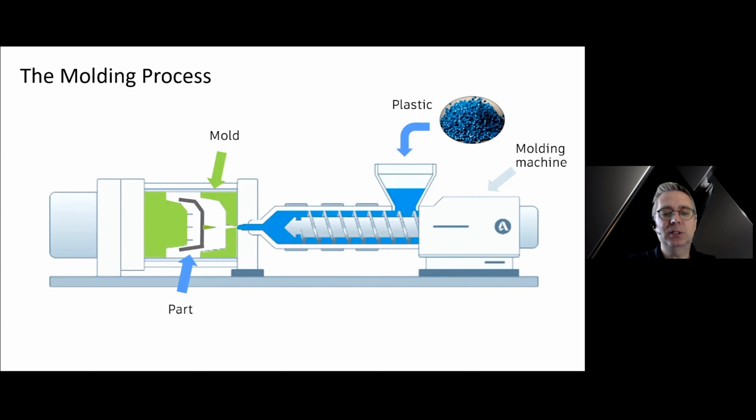So I just want to start with the basics, right? We've got an injection molding machine here. And we're going to start with the little plastic pellets. We're going to put them into the machine where they are going to be melted. Once they are melted and completely liquid, a side note on that, when we melt plastic pellets, they actually expand slightly by volume.